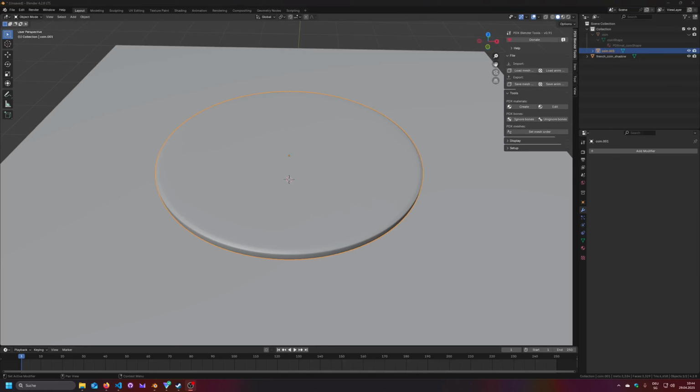Hello there, so let's improve your high poly shape again. For that I know two useful ways to do it. One of them is you add a modifier, and this should be a subdivision surface modifier. You click on simple and you put it a little higher and then click on apply.